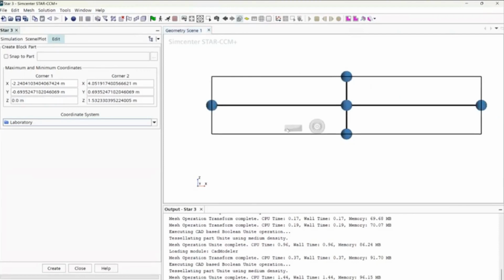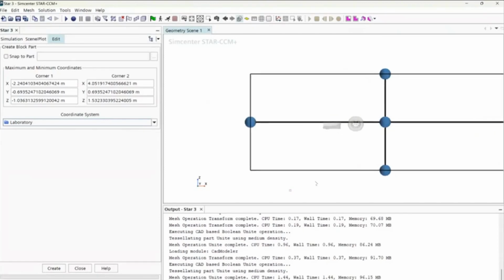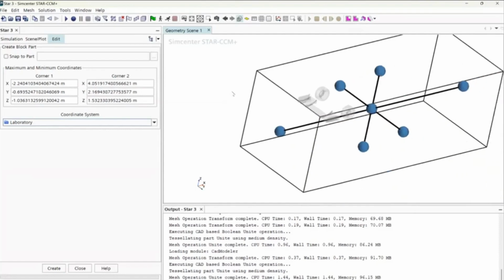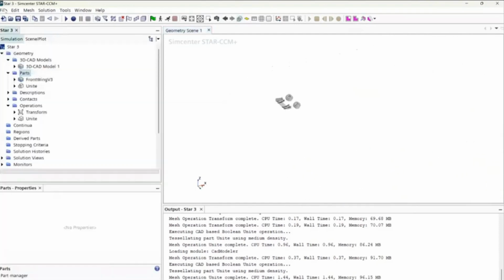But if we were to have, say, a wing, and we want to simulate this wing acting in the sky, we would do this, of course. Now, of course, this is all math: 4 heights above, 4 heights below, 4 lengths in front, 4 behind, and of course you want to remember width, 4 widths to the side. This is all math.